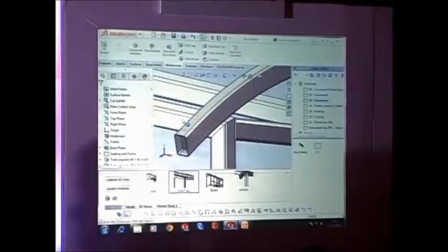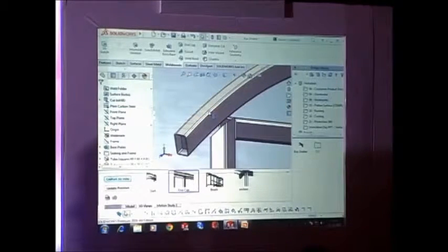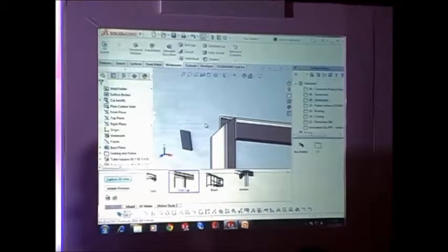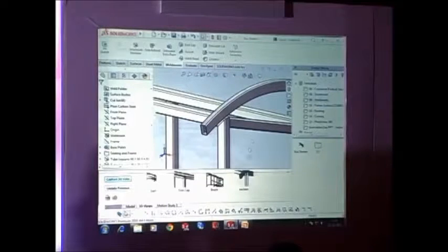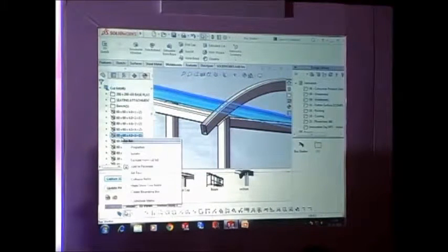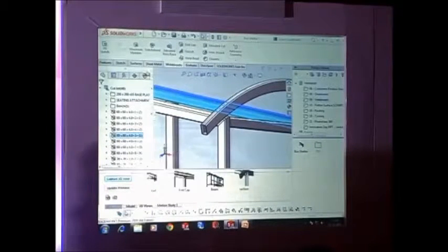Now we can easily hide individual bodies, not only bars, but also solid bodies as well as surface bodies. Shift tab provides a reverse process of it. Cut list has always been a powerful way to understand all the aspects of structural designs. Now SolidWorks 2016 introduced an enhancement of adjusting the individual column width and also the overall dialog.